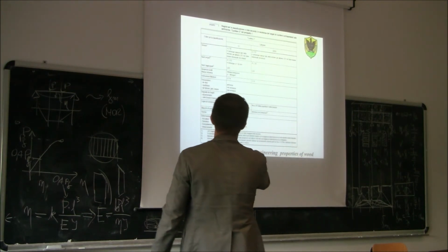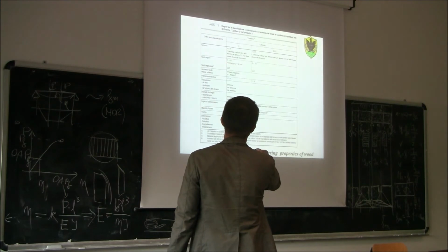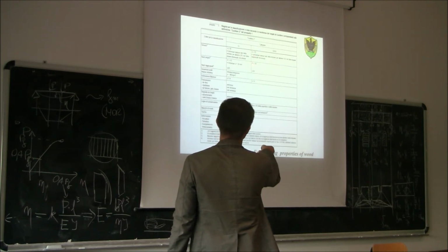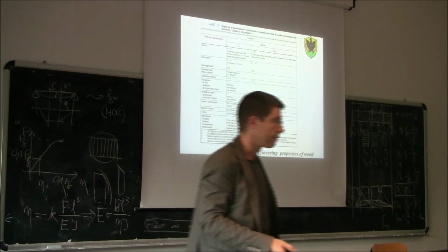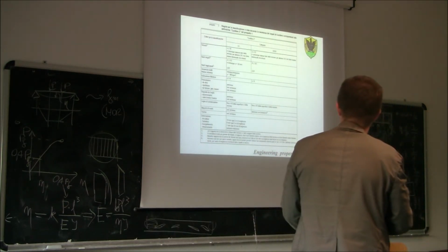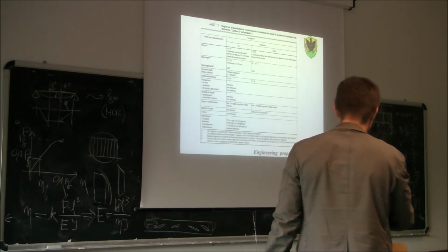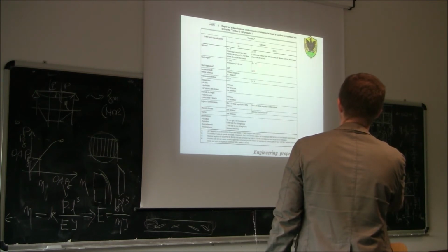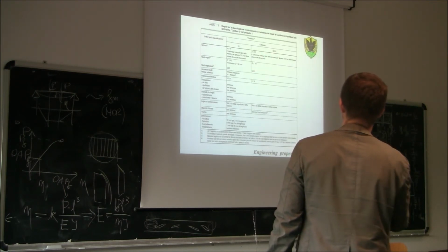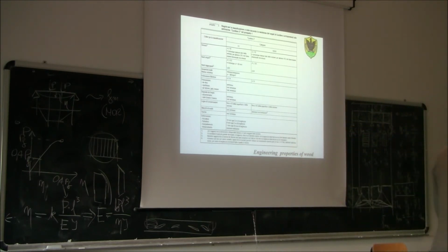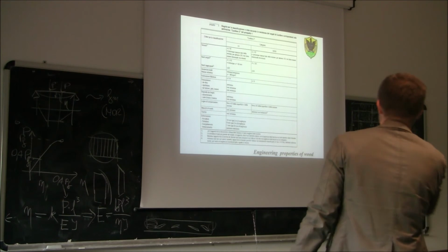Then we continue with knots. The area of the knots less than 1/5. We know that since this condition was not compliant, here we need to see if the area of the knot is less than 3 out of 5. So if it covers less than basically 3/5 of the whole width, then it can be S2 or S3. To be S1 it should be less than 1/5 of the width. Okay? And then you continue this way.